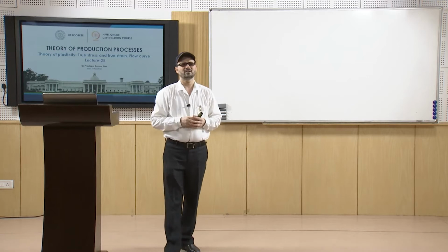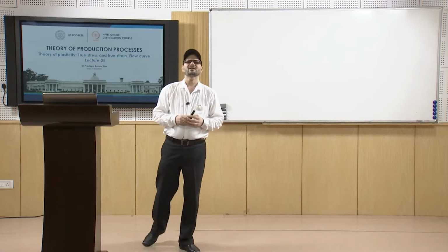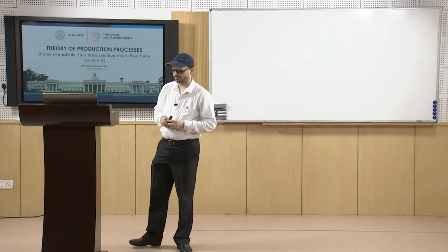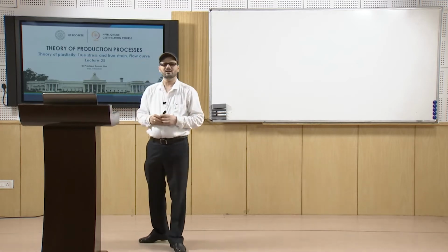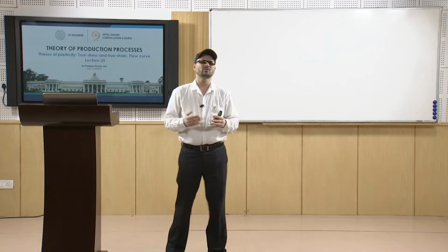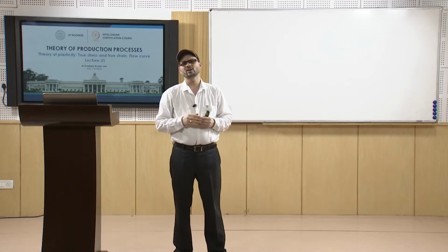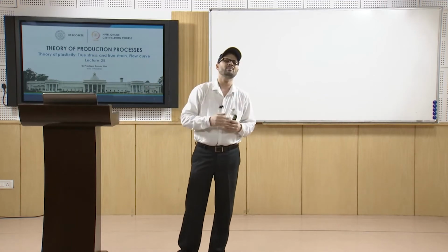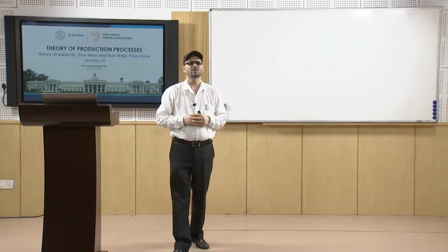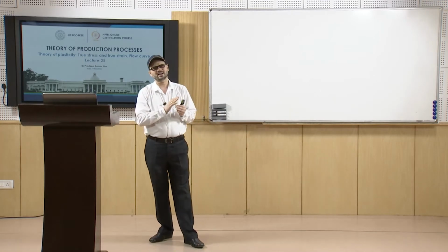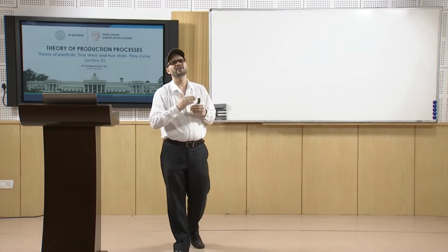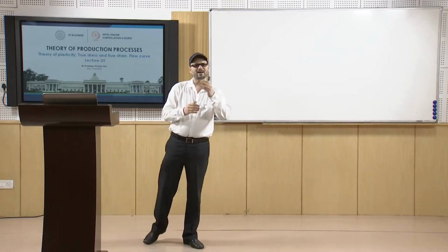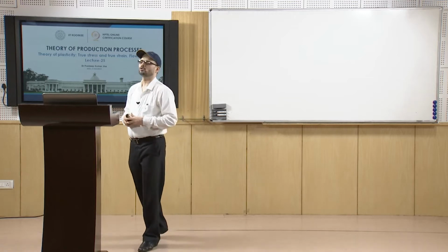That is how you define the elastic deformation. Whereas in plastic deformation, the reversibility is not there. Once you go into the plastic range, you are not able to come back to the original shape of the material. There is some permanent shape change. That's why you don't have the validity of Hooke's law.